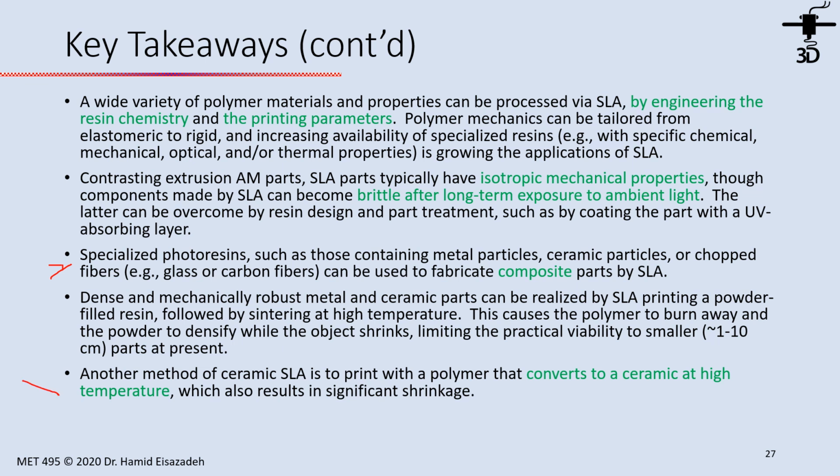The last point is that we can have ceramic SLA, so we can print polymer with the ceramic, but then later it converts to ceramic at high temperature. But this process has a lot of shrinkage that must be taken into consideration.